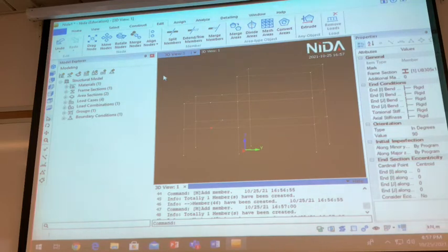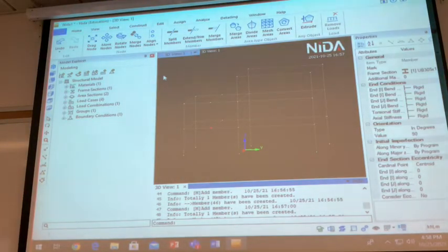This is a sign convention. This is the sign convention used for all structural analysis or most of the computer programs. Right-hand side. X, Y, Z, 1, 2, 3. So you can follow this one. X, Y, Z. That's right, okay? And also, when you define the moment, when this is positive, you should also follow the right-hand rule. Bending about this way and then this way. This is the sign convention used in the analysis and also the computer program, both, okay?